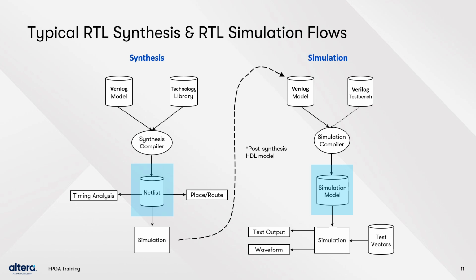In this case, the output Verilog file from the synthesis tool can replace the original Verilog files in the simulator. The same test bench and test vectors can be used for this verification. Additional simulation model files may be required depending on the synthesis tool. These can be provided by the synthesis vendor or generated by the synthesis tool along with the post-synthesis model.